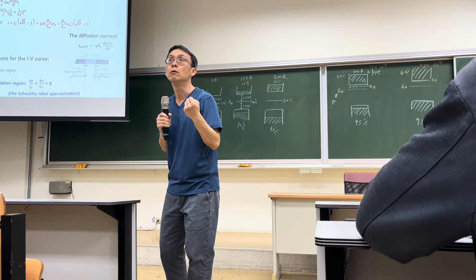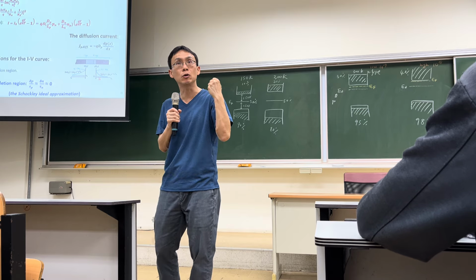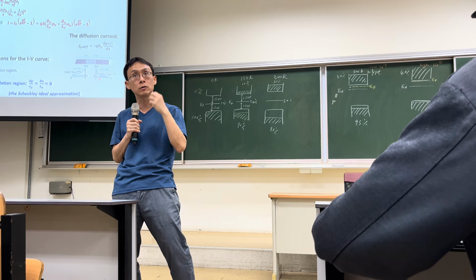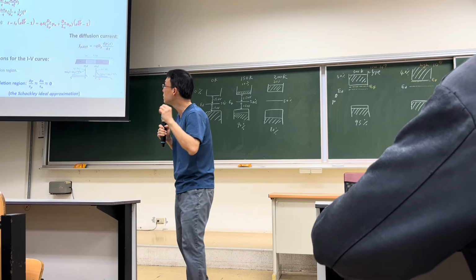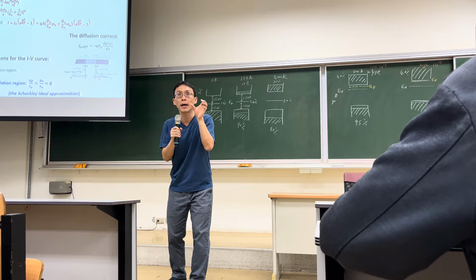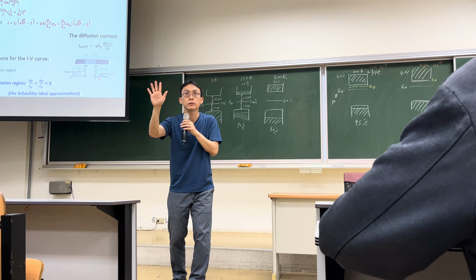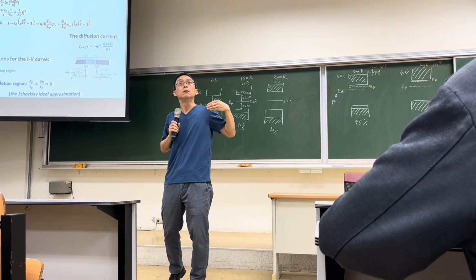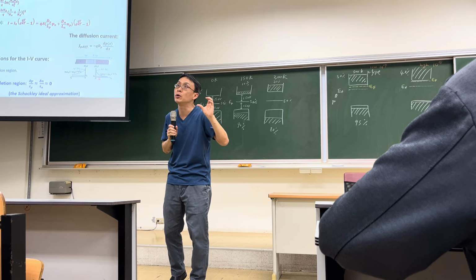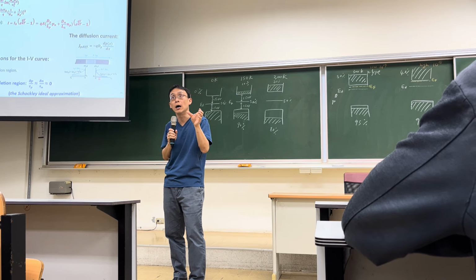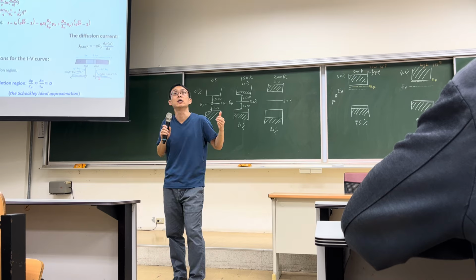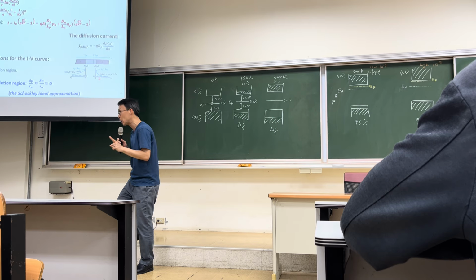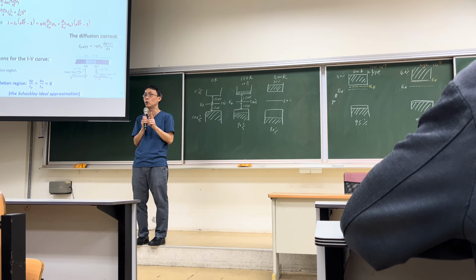Charge neutral region. When we say charge neutral, that means we have equal numbers of positive charge and negative charge, so the sum is 0. That means if you have applied a 5 volts bias to the diode p-n junction, all of the 5 volts will be happening in the depletion region. No voltage drop outside the depletion region, which is the CNR, right? So that's the assumption. Remember, that's not always the reality. I will show you what happens if this assumption is broken.